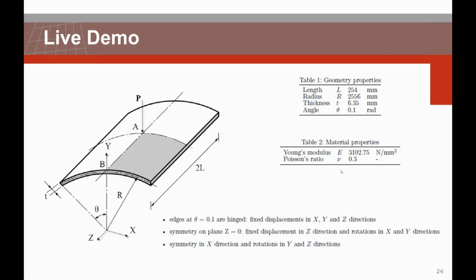We are going to study the behavior of a hinged plate panel subjected to a point load in the center. Due to the symmetry of the model, we are just going to model one quarter of the geometry, the one depicted in gray. During the live demo, we will highlight the advantages of choosing a proper nonlinear iterative scheme in conjunction with advanced techniques like arc length and their corresponding settings to obtain a solution for a highly nonlinear model.